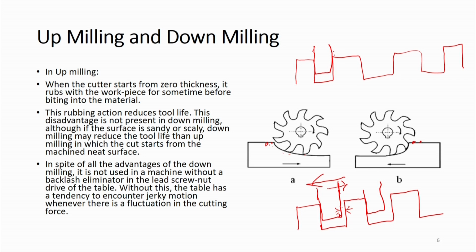The gap is still there, but I provide another nut here. There are many nut threads, but I am just showing one. In this one I align in the other direction. I can put a special arrangement between the two nuts, so that this portion keeps pressing in this direction and the other portion keeps pressing in the opposite direction.